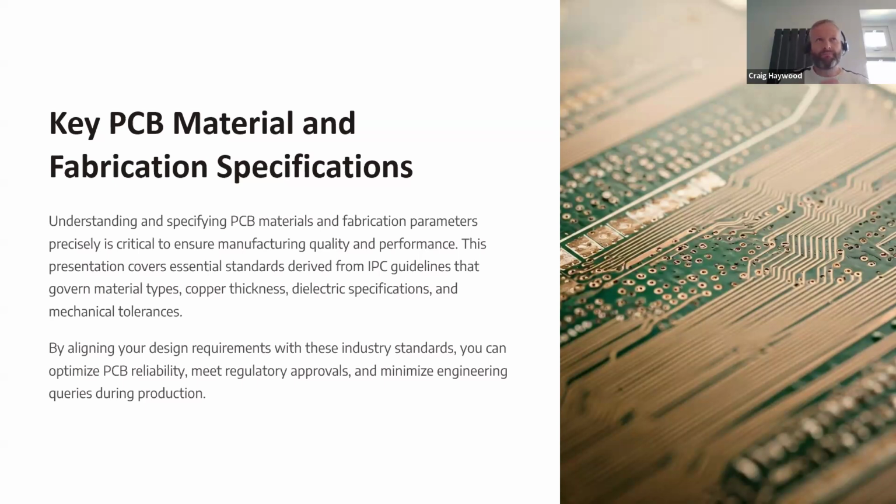Bear in mind as well that material types from time to time go obsolete or get upgraded. So if you have on your drawing notes that it must be one particular material, and then this material type goes obsolete in the end, we are back to square one and looking for different suppliers again. So highly recommended, follow your IPC guidelines.